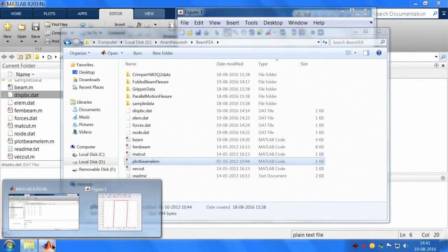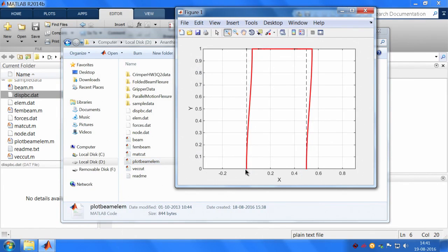that takes into account the slopes at this first node and second node and the displacement and interpolates using a cubic function, because for this beam element in finite element analysis we have used cubic shape functions, and that is what is used to interpolate in between. That is why we get the nice curve that you see in the real device also, and this applies to any complex beam compliant mechanism that you make up. It will show you the interpolated beam also. So, you have degrees of freedom only at the ends, but you would know the deformation at every point.